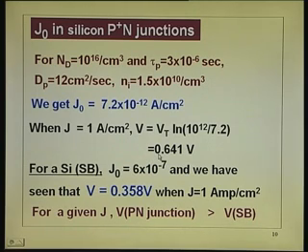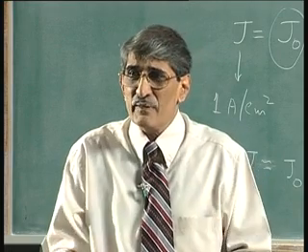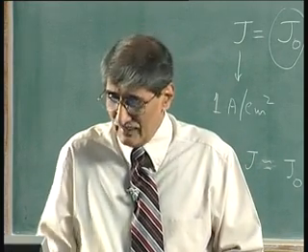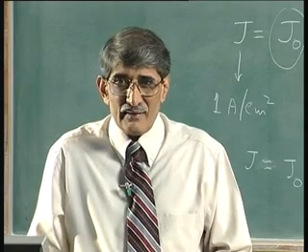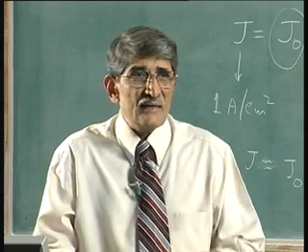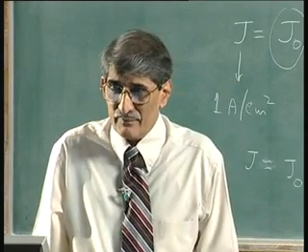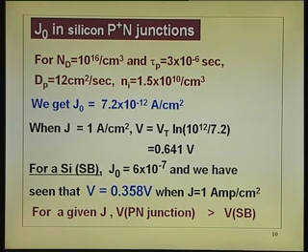So, you are used to hearing that the cut-in voltage of a silicon PN junction is about 0.6 or 0.65. That is the implication of that. About that current range, you get that voltage drop. It does not mean that the diode starts conducting at 0.6; it conducts even otherwise. If you go to 0.1 amperes per centimeter square, you will get a much smaller voltage than that. It is conducting, but when you are using that particular range, you get 0.64.